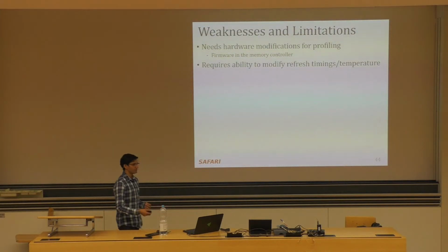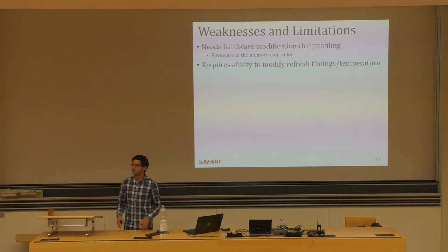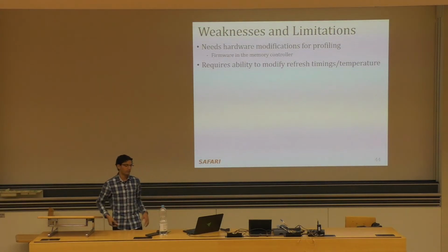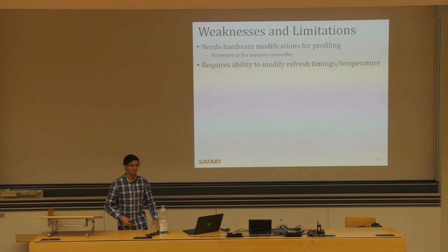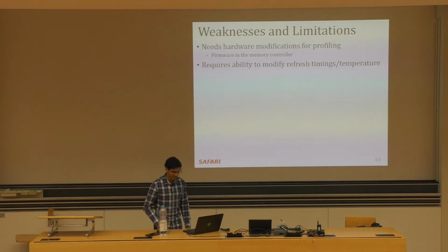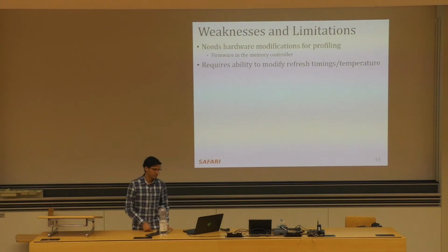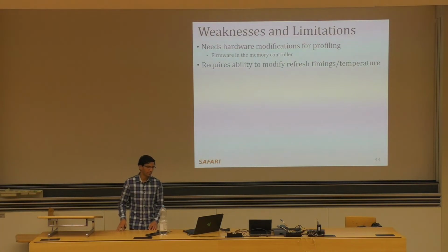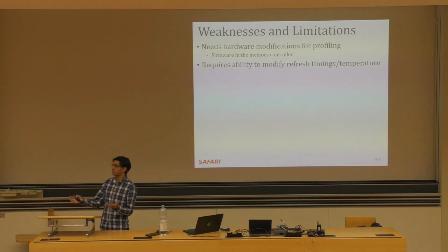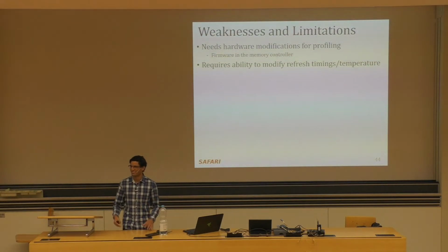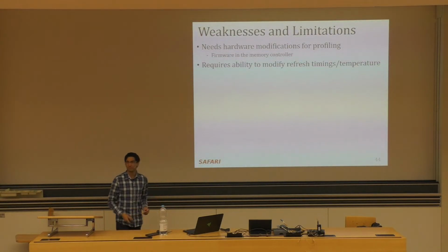Another weakness is that REAPER requires the ability to modify refresh timings and temperature in the first place. Right? So as I just said, not all CPUs will allow you to change the refresh interval. And if you can't change that, then you essentially can't apply this profiling methodology, right? Similarly with temperature. So let's say I'm trying to profile my laptop here. Short of having like a hairdryer and a fan blowing on it, there's no real way I can manipulate the temperature at will, right? And so then I can be passive about it and try and profile based on what the passive temperature changes are, or I can try and run some really intense code and heat up my machine or something like this. Yeah, so this is another limitation of the work.